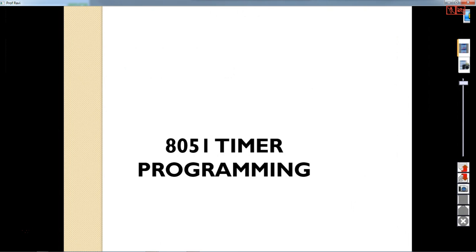which has onboard timers. In 8086 what we did is we have interfaced 8254. So 8254 is a timer IC. So that we interface to 8086 to facilitate, like to count external events or to provide timings and all.